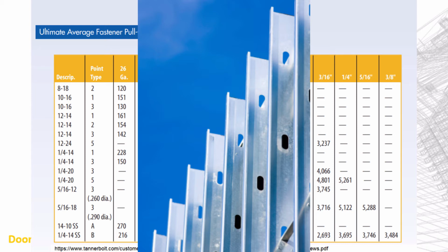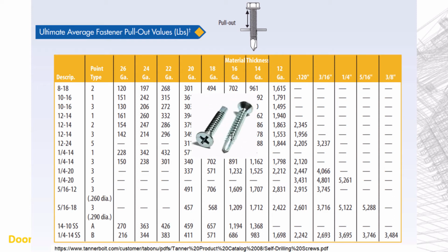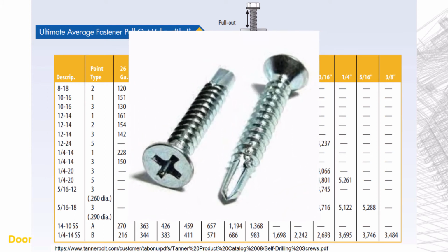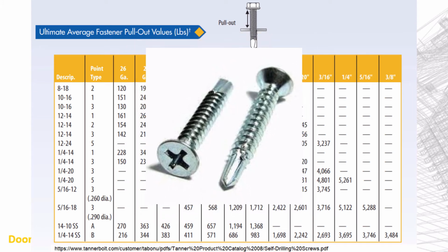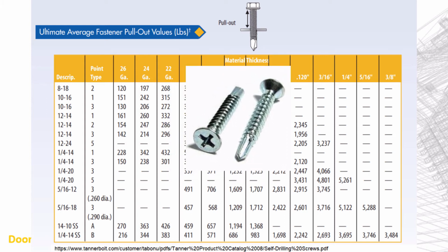Metal studs come in a variety of sizes and thicknesses. Typically, 20 gauge metal framing is used at the interior for non-load bearing walls in commercial buildings. For our purposes at Door and Glass, we're going to be using the self-drilling number 3 tip flathead countersunk, similar to the pictured screw. It's not going to be a Tapcon at the top of the frames attaching to metal.